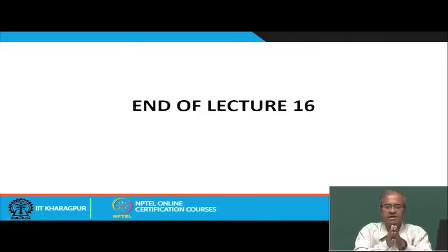So, I think in this lecture we have discussed some of the variations of Lee's algorithm which can help it to save space in terms of storage, to run faster, and also some simple way in which you can extend the basic algorithm to handle multi-pin nets. Okay. Now, in the next lecture we shall be looking at some other approaches which are more efficient in terms of the running time. Thank you.